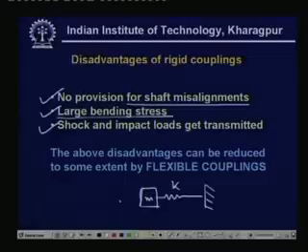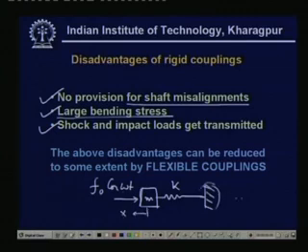Let us see, if you have one mass and a flexible object which has flexibility, that is stiffness k, if you have this force F0 cosine omega t, that is a variable force with a frequency omega, then you see the total force transmitted on the other side, that is on the base, will be k times the displacement, and that will be equal to F0.